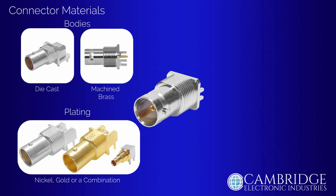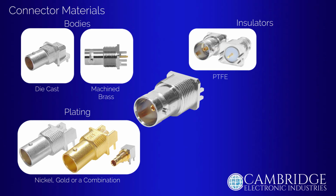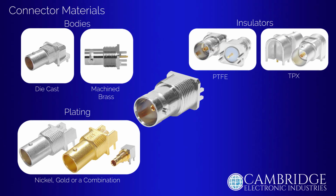The insulators surrounding the contact pins can be produced from several materials. The most common is PTFE, which is white in appearance. Connectors in the Pathfinder range use TPX, a transparent material that allows light to pass through, potentially offering a guiding aid to engineers working in dark spaces. A third option is PEEK, valued for its radiation resistance, making it well suited for nuclear sector applications.